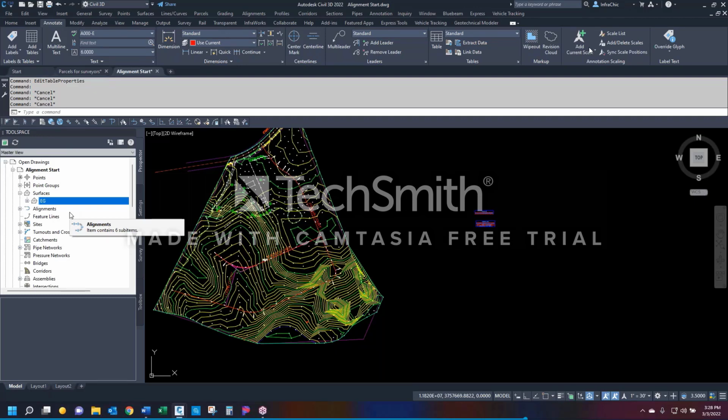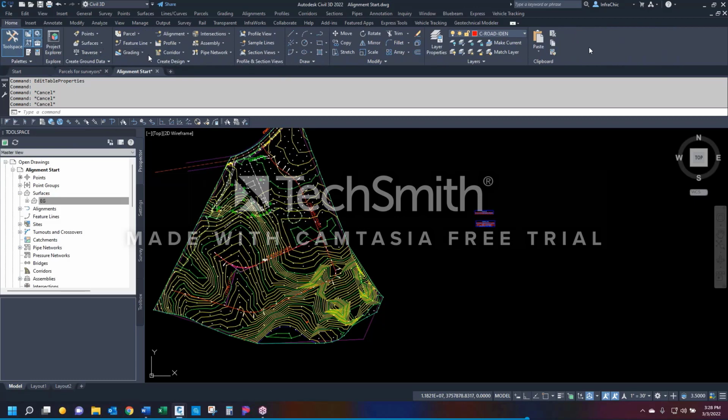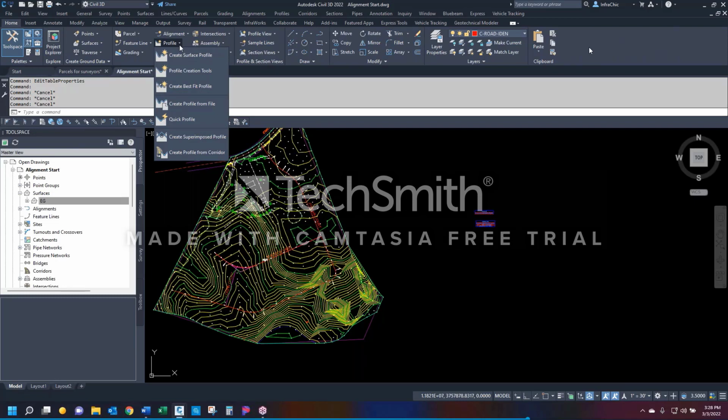You can't just say, I want to put a profile grid out there and draw my own. That don't work, ever. Even if you have the alignment made, it don't work, ever. You must sample a surface before you can go, now I can draw my own. Okay, so let's go ahead and do that. So on the Home tab of the ribbon, back up here under Create Design, the next one under Alignment is Profile. So we have two options with Profile, Create Surface Profile, which we'll do, and Profile Creation Tools.